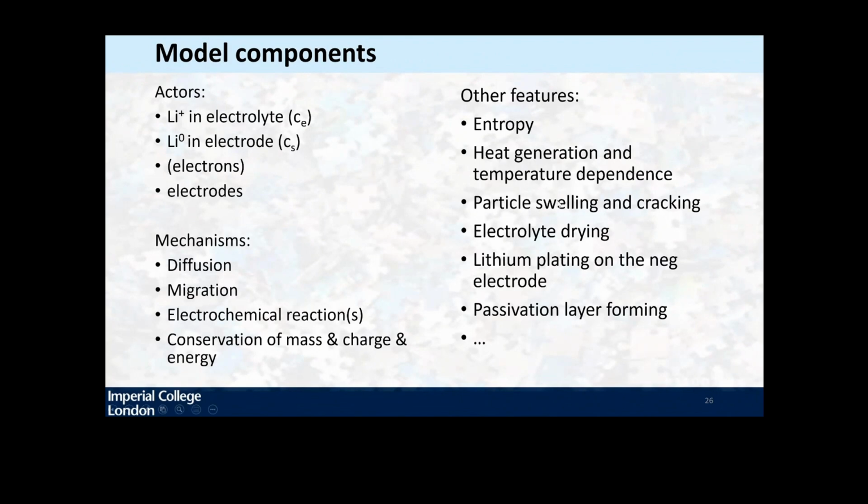We may wish to start looking into degradation. Remember the picture with everything happening at the same time. And I just put here a few of the degradation mechanisms to ring a bell that we need this kind of model to start seeing how these mechanisms may play a role in the performance of the cell. So particle swelling and cracking is something we may wish to look at, and this has been done in Billy Wu's group. Electrolyte drying is one of the very important mechanisms for sudden death of batteries.